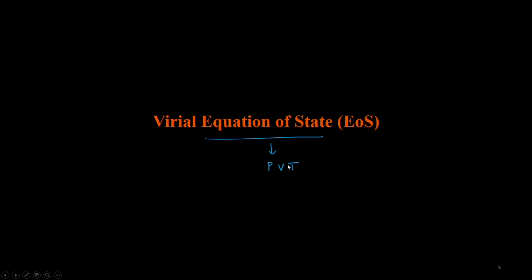Now, when we talked about the ideal gas early on in this course, we looked at the virial equation of state, and we said that it is sort of a power series expression for the PV relationship. So for example, the product PV can be expressed as A plus BP plus CP squared, etc. And if I factor out A, it would be A times 1 plus B prime P plus C prime P squared plus so on.